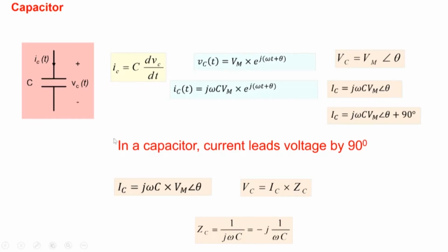So that's the capacitor. So anywhere in the circuit, if you're doing sinusoidal steady state analysis using the concept of phasors, wherever you see a capacitor, replace it by a complex number 1 over j omega C. So that denotes the relationship between voltage and current across a capacitor.